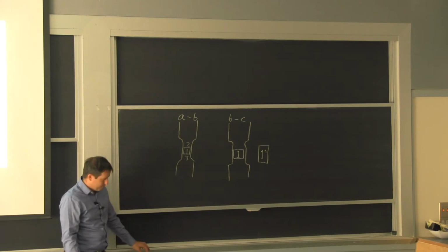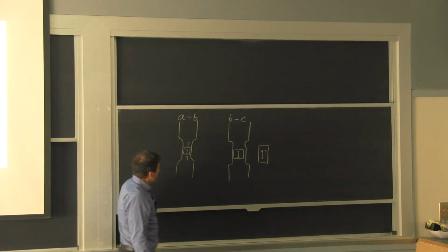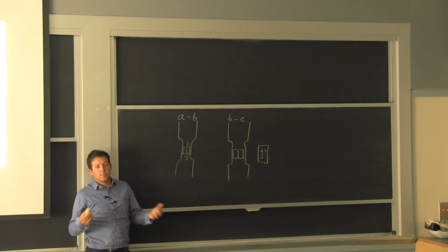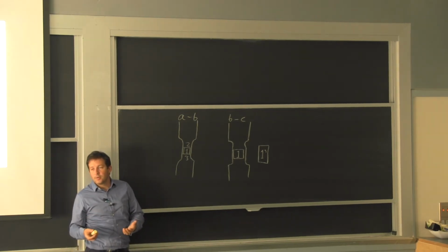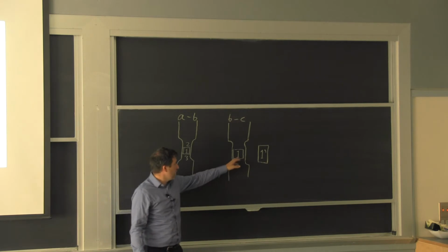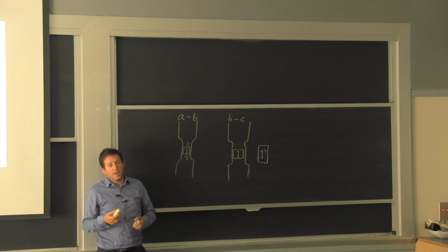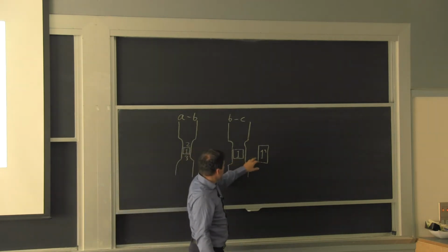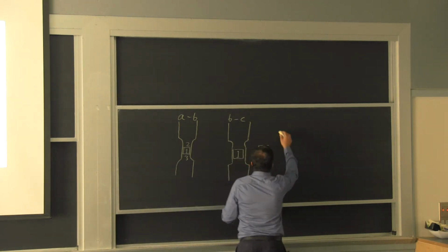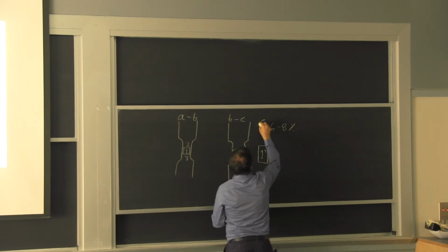If you've heard of bulk metallic glasses, for example, on metals, they behave this way almost right from the beginning, because it's completely disorganized and there's no real way for the material to gain strength by deformation, so it will start to neck and localize in the middle or in one area right from the beginning. It doesn't mean it breaks right away, but what you're measuring is the straining of one area. And maybe on a bulk metallic glass, those I've studied, say you get 6 to 8 percent elongation at break. So say the strain to fracture.